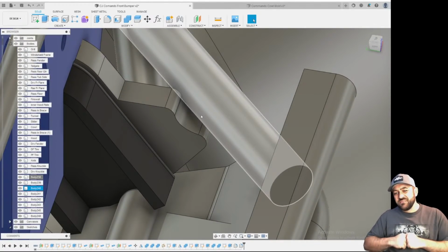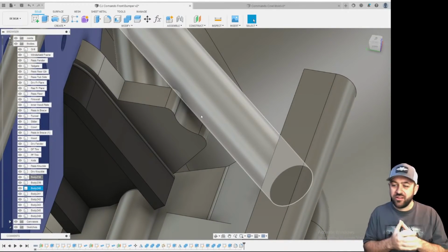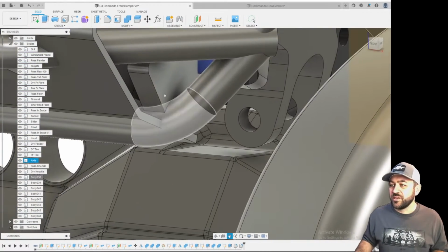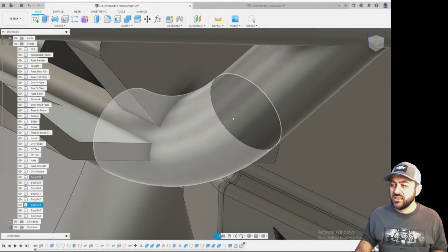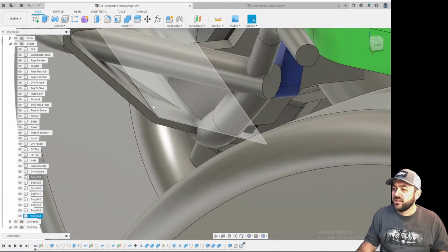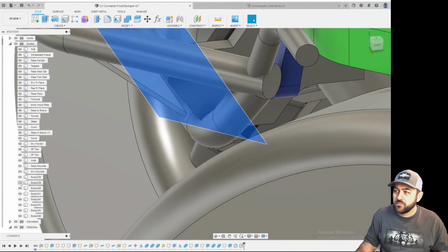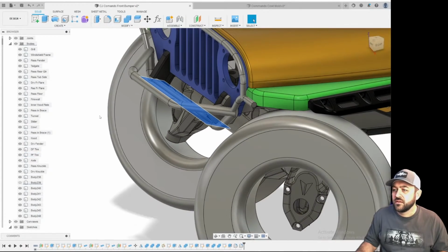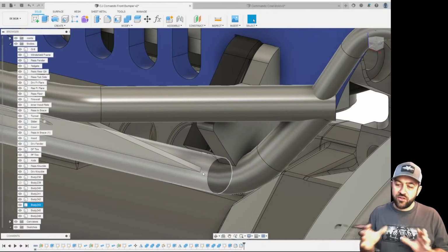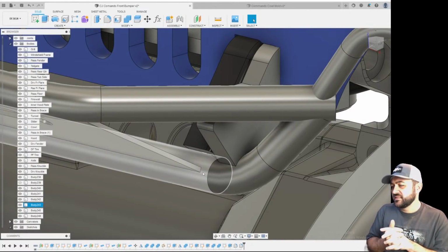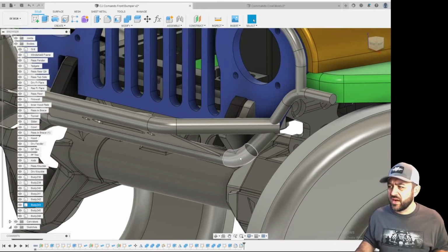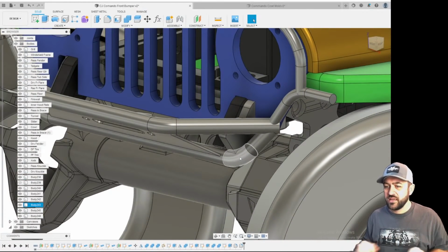I could maybe adjust that. Maybe I'll leave that piece of material there. It's hitting at such an extreme angle that I probably do want to capture it. But this one down here would give me that nice cradled look. But that would cradle the bottom, give me a good place to actually braze this onto. I'll probably braze this whole bumper rather than TIG weld.